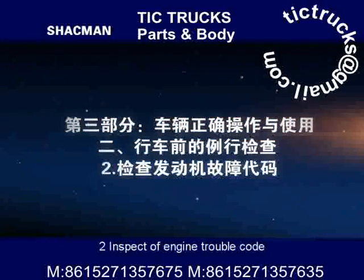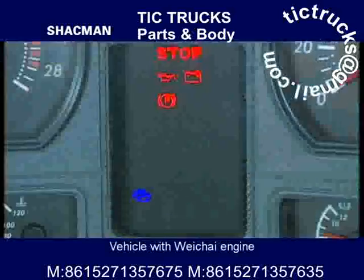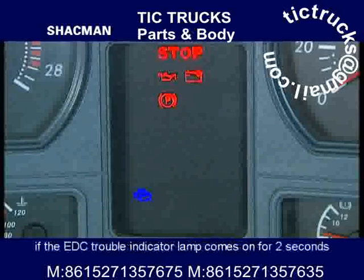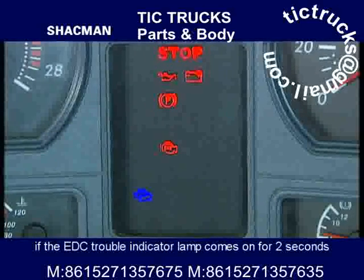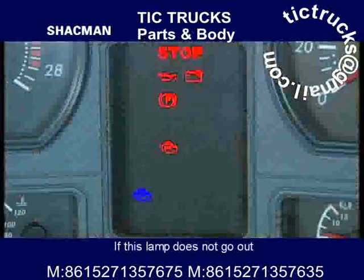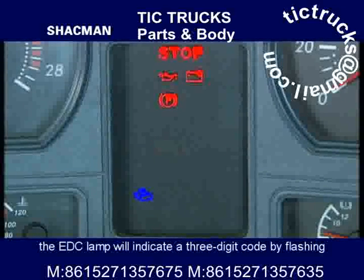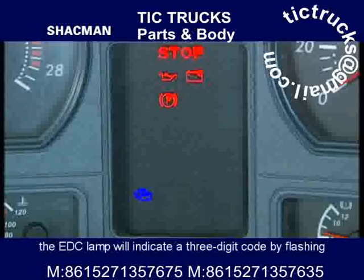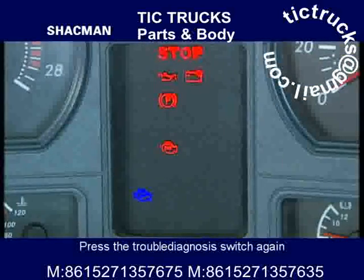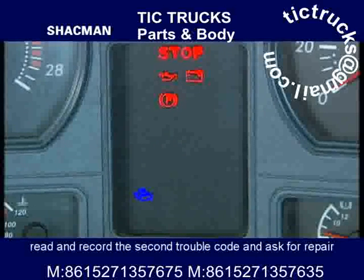2. Inspect engine trouble code. Vehicle with Weichai engine. Turn on the ignition switch. The engine is in good condition if the EDC trouble indicator lamp comes on for 2 seconds and then goes out. If this lamp does not go out, there's trouble. Press trouble diagnosis switch. The EDC lamp will indicate a 3-digit code by flashing. Press the trouble diagnosis switch again. Read and record the second trouble code and ask for repair.